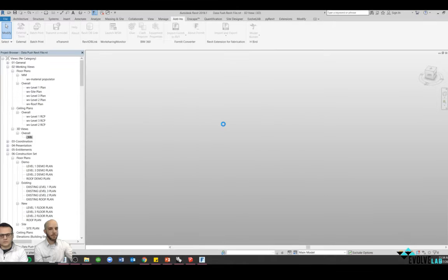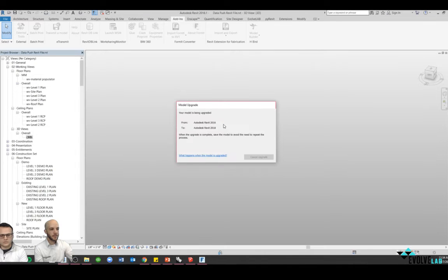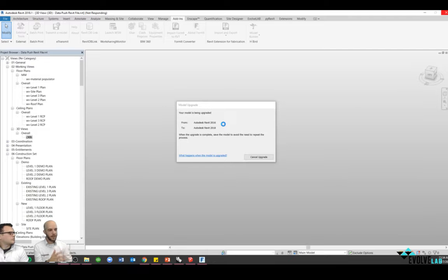What you'll probably notice about this workflow is that it's very similar to the SketchUp to Revit one. You're bringing in a FormIt mass to a Revit mass, and then from there you start doing wall by face, floor by face, and roof by face on that mass in the Revit environment. That's really less about a SketchUp to Revit workflow and more a DWG to Revit workflow, a 3D DWG file being brought in.